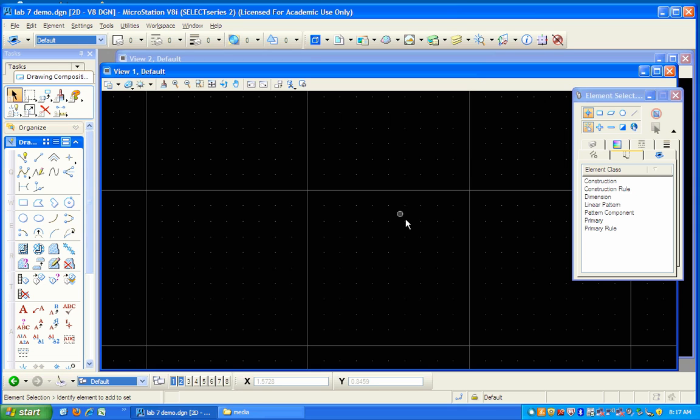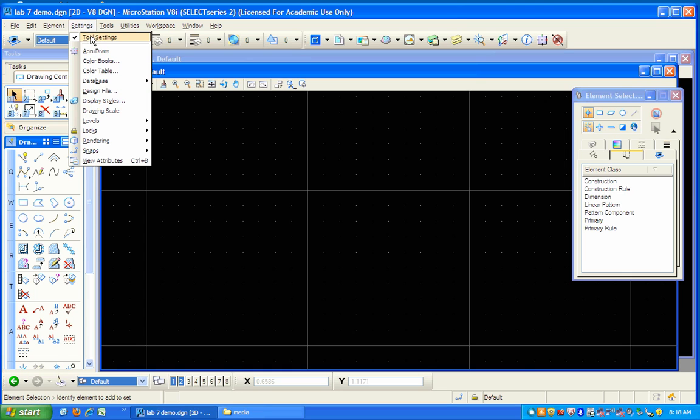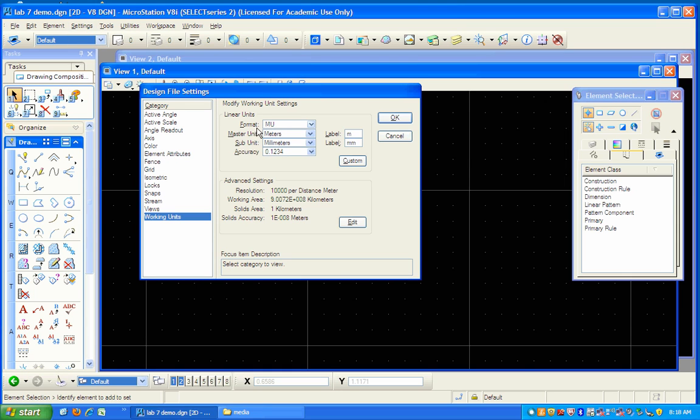Okay, and then this design file also should include two sheet models, one for the rocker arm printout and one for the wall printout. So let's set this up. This default model I have open right now is just a brand new file with the seed 2D in it that we always use with meters. We're going to change the settings a little bit though. Instead of master unit meters, we're going to use a master unit and subunit designation of meters and millimeters, and that'll work just fine.